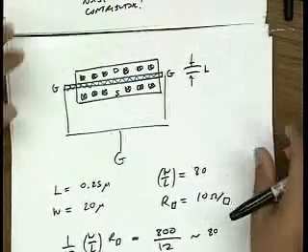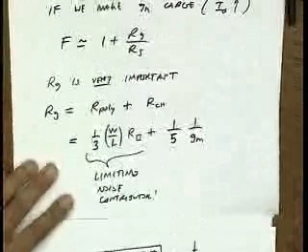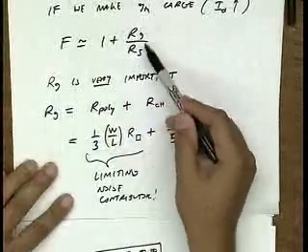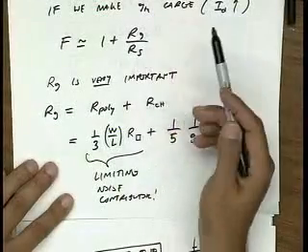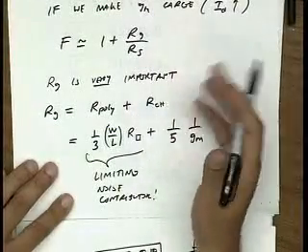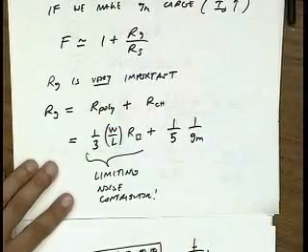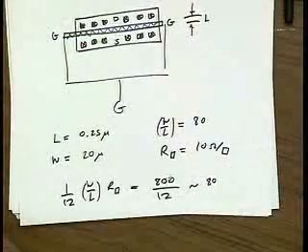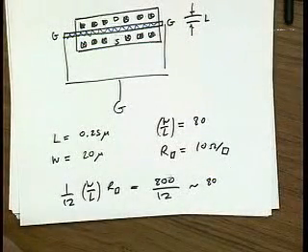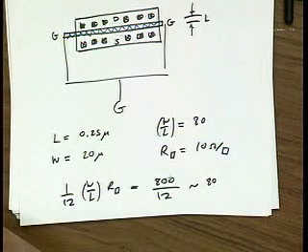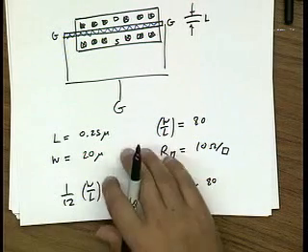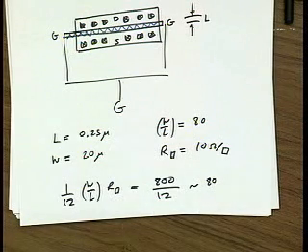Now if I use this limiting value for my noise figure, the limiting value is 1 plus Rg over Rs. Rg is becoming comparable with Rs, and so the noise figure is already bigger than a factor of 2 just because of this gate resistance. Okay. So what's a very simple solution to get around this? Maybe somebody who doesn't know the answer, who's guessing. Anybody want to venture a guess? How could I reduce this gate resistance and still keep the same transistor width?